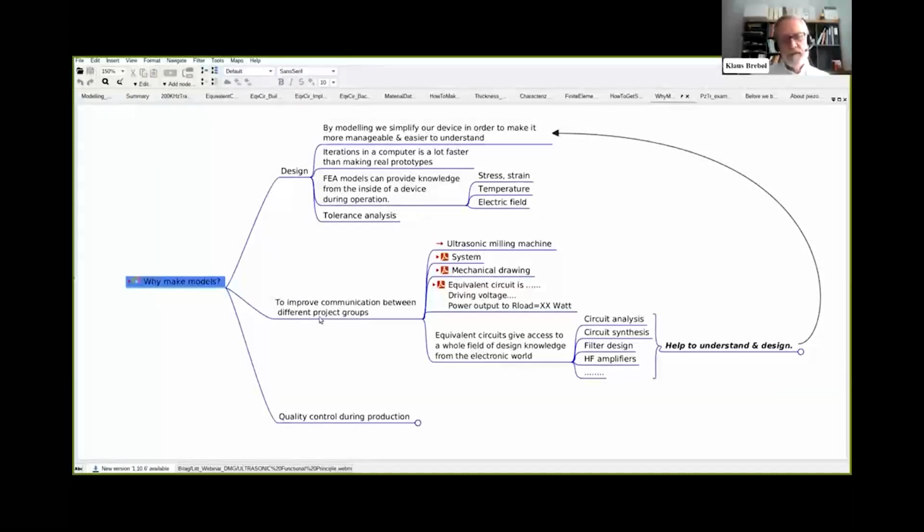This is the spindle of a milling machine. You have the tool here. It's being rotated by the spindle. And at the same time, since this is an ultrasonic machine, we have a power transducer in here, which is being supplied with electric power through a rotating transformer. That is a transformer with a stationary primary and a rotating secondary, and there is an air gap here.